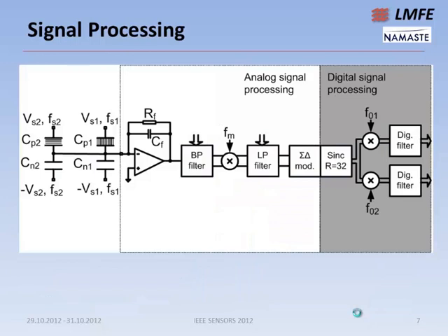Now, of course, we have to measure this small capacitive difference, and we would like to measure differently functionalized sensors at the same time. So here is the principle of operation for two capacitive pairs: one functionalized and one unfunctionalized, and another pair which has different functionalization. Both are connected to our transimpedance amplifier, some bandpass filter, some AD conversions, and some digital signal processing.